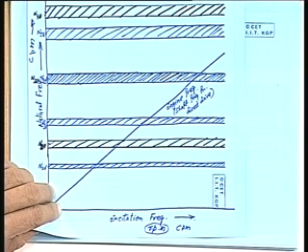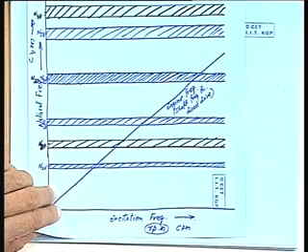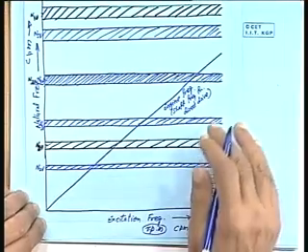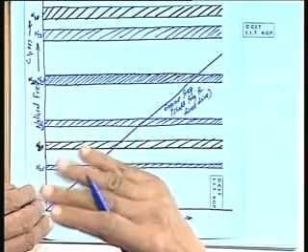In that case, the frequency will be lower, because for say 10 RPM of the engine it will have 5 RPM, if the gearing ratio is 1/2 or something, so it will be 0.5. So usually for ships, when you have the gearbox, the shaft RPM will come down.